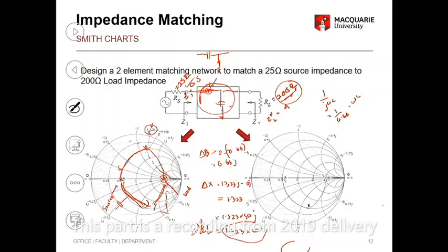So you could have two types of matching circuits for this, but you will pick the one you want based on whether you want to pass DC or not. Did you get my point? Because previously I talked about this too. So this is a DC block, right? If you want to block DC, you will use this circuit. If you want to pass DC, you'll use this circuit.